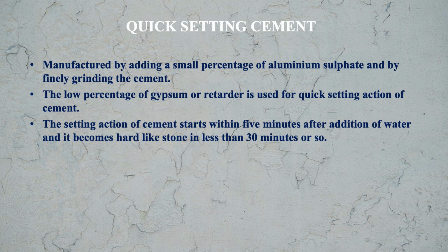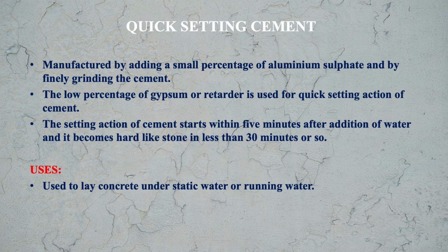You see here that its initial setting time is 5 minutes and its final setting time is not more than 30 minutes. It is used to lay concrete under static water or running water. So here we covered all 12 types of cements basically.